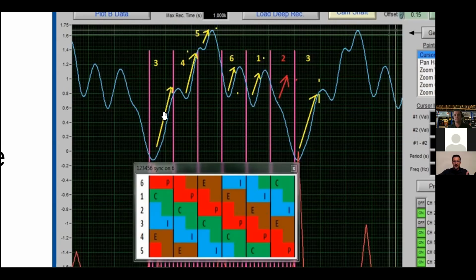It's the same reason if you measure vacuum at idle on a healthy engine, you might see something like 21 inches of vacuum or 19 inches of vacuum. But if you hold it at 2,000 RPM steadily, vacuum increases to 22 inches of mercury or more. Why? Because the speed of the engine allows for a stronger vacuum to build inside the manifold as we consume more air. So here the engine is picking up speed between here and here. Vacuum is starting to intensify in the manifold.